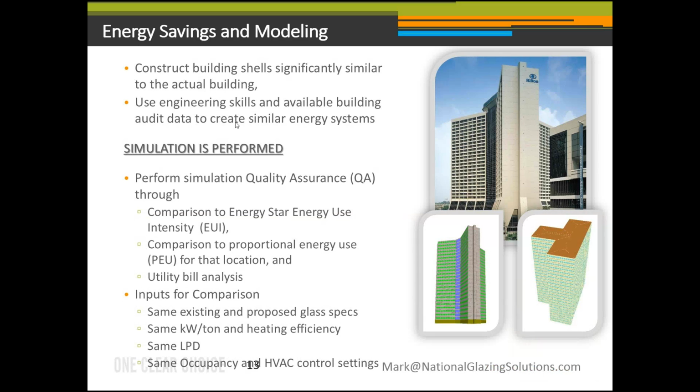Many of you have some experience with estimating energy savings. Energy savings calculations can be as simple as a company Excel spreadsheet that they use for lighting retrofits, to performing energy modeling using data from an investment grade audit for a deep retrofit. When we at NGS consider energy modeling and energy simulations for fenestration, we start with a requirement that we must be able to construct a building shell that is significantly similar to the actual building. It doesn't need to be perfect, but it must be significantly similar.